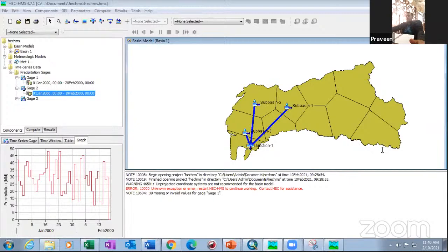So it will of course have a disadvantage, but still you can calibrate lag time and reach a certain good value. Both have advantages. If you know your channel values well, go for the Muskingum method. If you do not have information about your reaches, simply use lag time. In that case it also doesn't affect your results much.